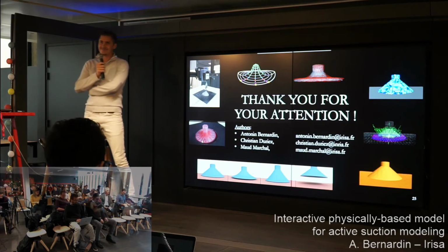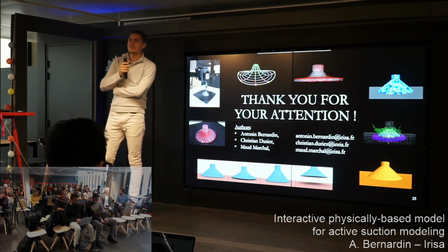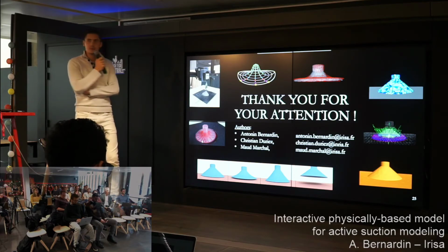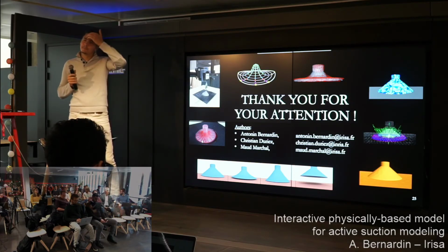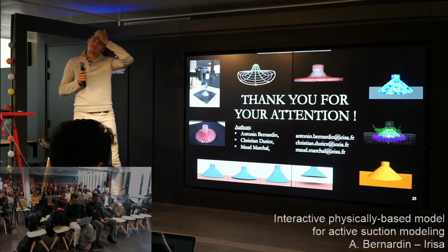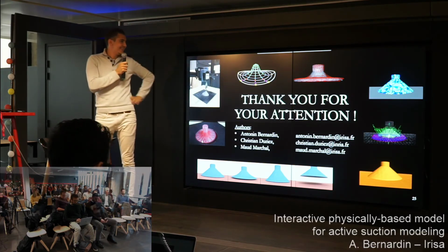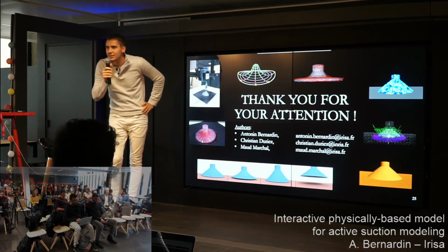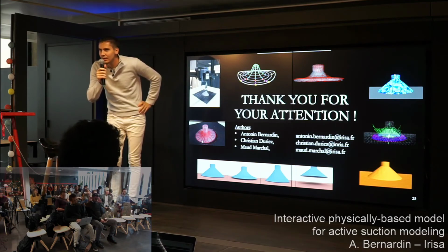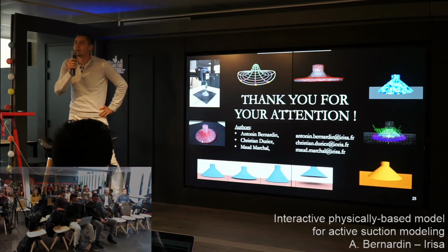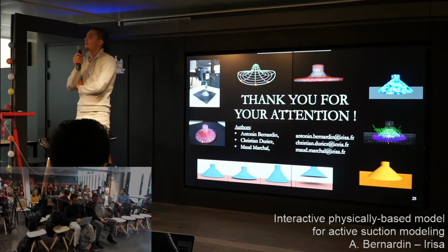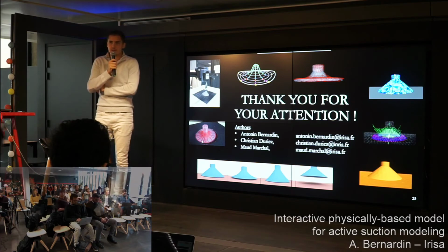Hello. Just a question regarding the thickness of the membrane of the cup. Is it problematic to mesh with tetrahedra? Is it quite thin? Could you, for example, use a shell model to represent it? I'm asking if the cup is very thin, maybe it's quite challenging to mesh it with tetrahedra. Or you don't actually have problems with that?